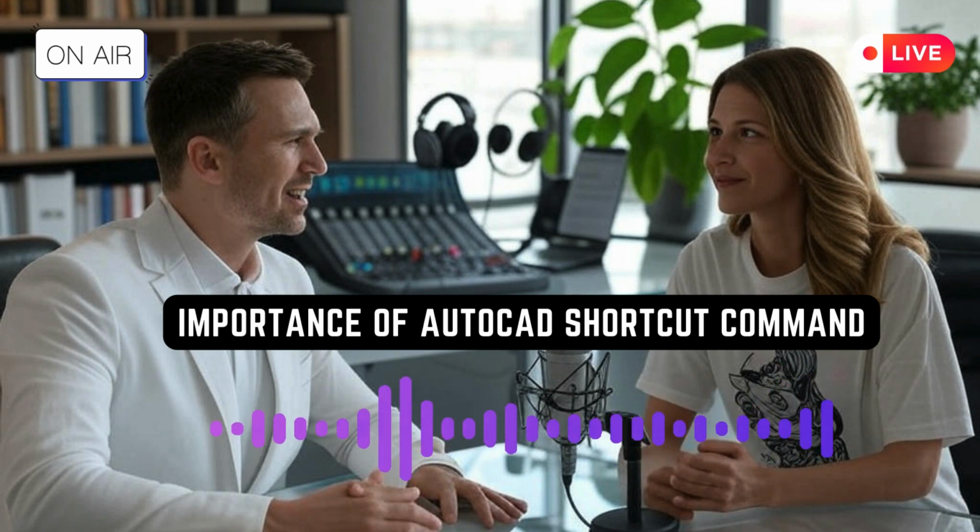All right. So let's start with the basics. What are these magical shortcuts we're talking about? Basically, they're keyboard combinations or aliases that can execute commands instantly. So let's say, for example, you want to draw a line. Instead of going up to the menu and clicking the line tool, you just type L and hit enter and boom, you're ready to draw your line. Wow. So you're speaking AutoCAD's language. And the more you speak that language, the faster you can communicate your ideas and get things done.